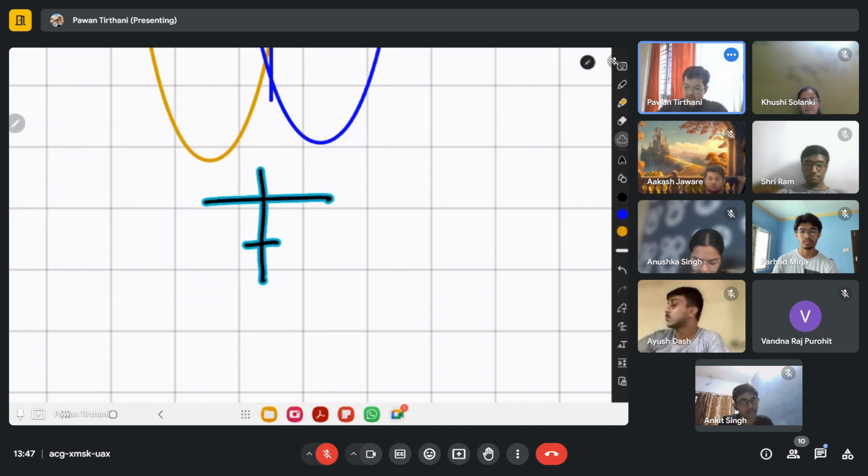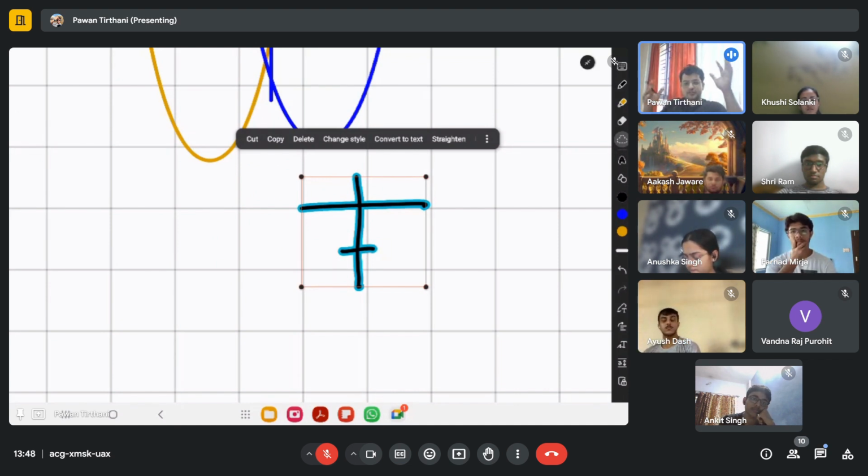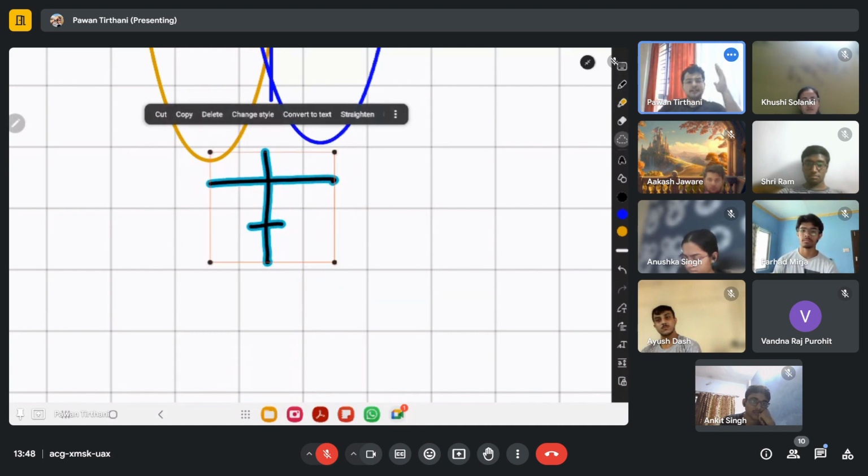If I happen to receive more of the 150 hertz signal, my equipment is sensing more of 150 hertz signal and less of 90 hertz signal, that means the equipment knows that I am on the right hand side of the center line. If I'm receiving an equal amount of modulation, that means I'm bang on the center line. I'm right on the extended runway center line. I'm nose to nose. Right?